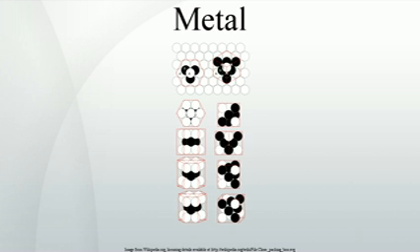This irreversible change in atomic arrangement may occur as a result of the action of an applied force, or work. An applied force may be tensile (pulling force), compressive (pushing force), shear, bending or torsion (twisting) forces, or a change in temperature (heat). A temperature change may affect the mobility of the structural defects such as grain boundaries, point vacancies, line and screw dislocations, stacking faults and twins in both crystalline and non-crystalline solids.